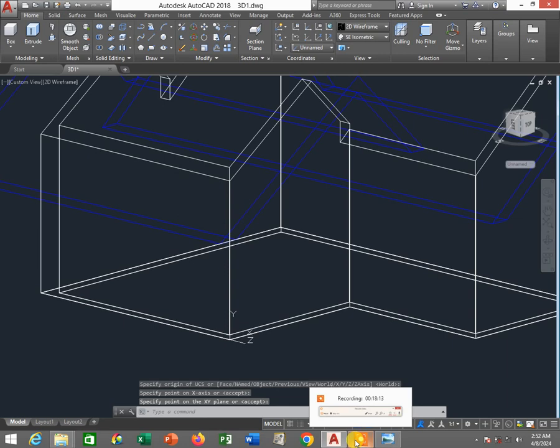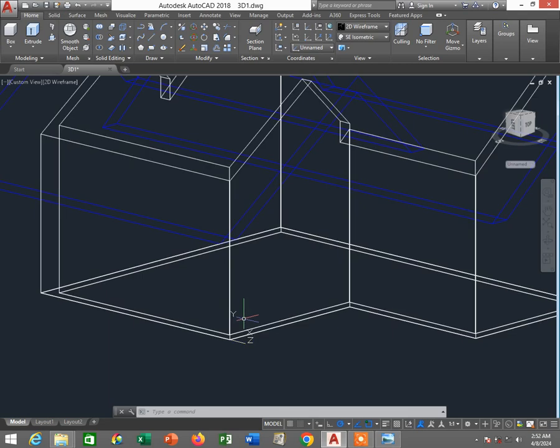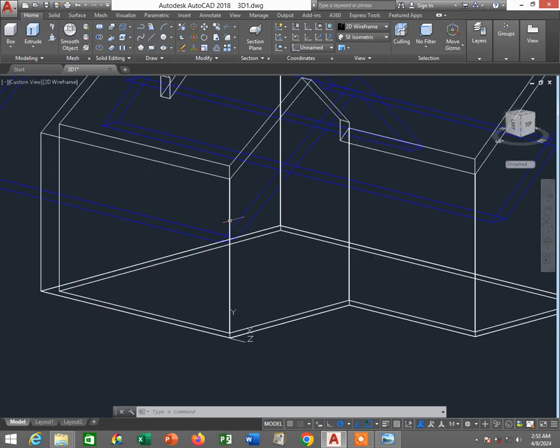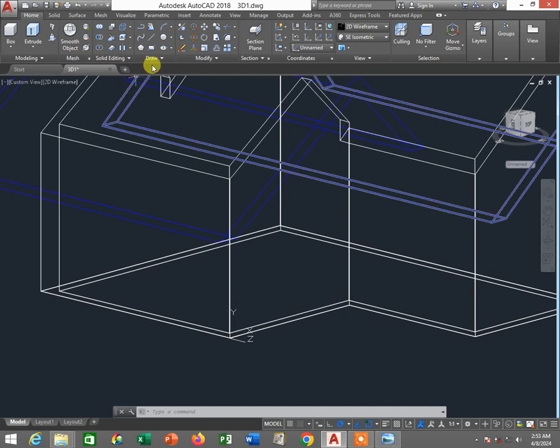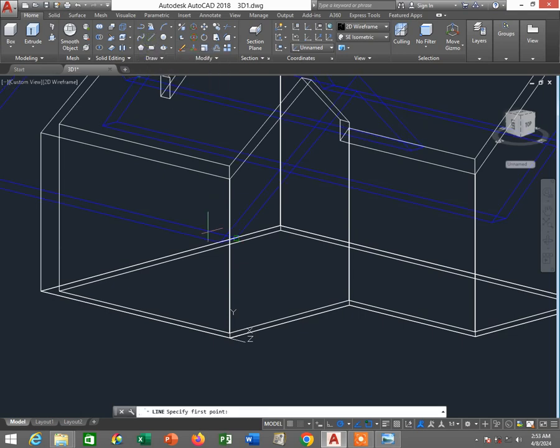So you can actually draw on your work plane by changing your UCS. Of course you can draw it using a line. I can just track over here a little bit, and then go up. 2100 is the height of a door, so I polar track over here. Let's say I just make it slightly bigger, maybe around 1002, enter. That's my door. Go down 2100, enter, and just connect it over here.